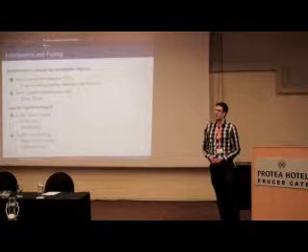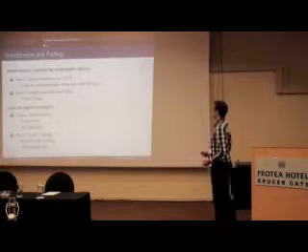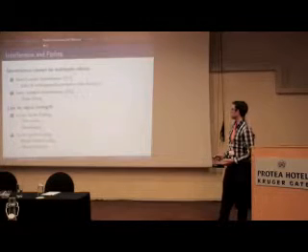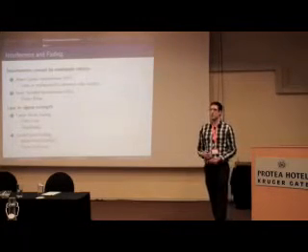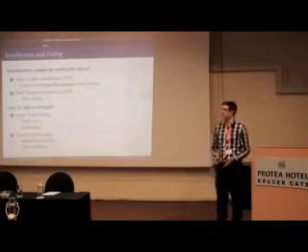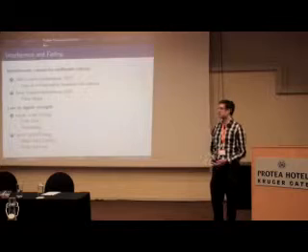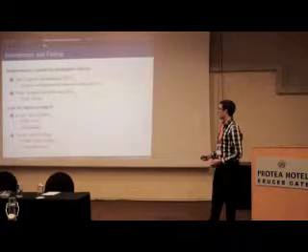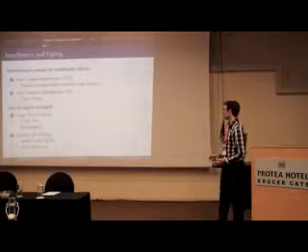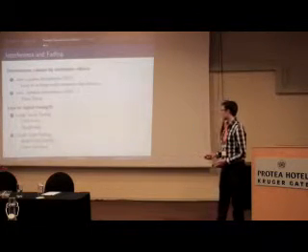More problems in the wireless channel are interference and fading. We have intercarrier interference. This is caused when there's a loss of orthogonality between two subcarriers. Then there's also intersymbol interference. This is caused when two distinct paths arrive within the same short time period at the receiver. Then we also have a loss in signal strength caused by large and small scale fading. Large scale fading is path loss, where we have an increasing distance between the sender and receiver. And then we also have shadowing. Small scale fading includes fading due to multipath effects, and then also time variance.